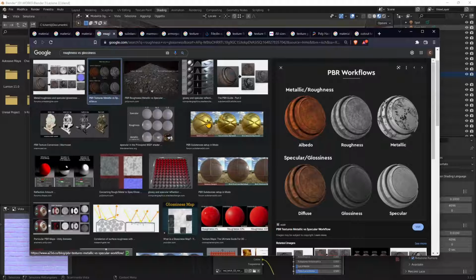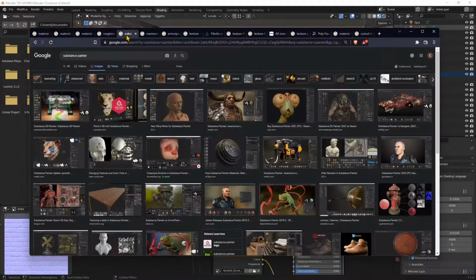While in the previous video we only worked with one single value, like the color value, or one single parameter from black to white, when we use textures, we use a variety of pixels. These can be colored pixels in the case of diffuse, which in other software is called albedo, or the color layer. If you use a roughness texture instead of a single value from black to white, you get a different response, which is not uniform. It behaves according to the pixels it sees. Don't worry about all this. If it's too complex, we're going to see it in action shortly.